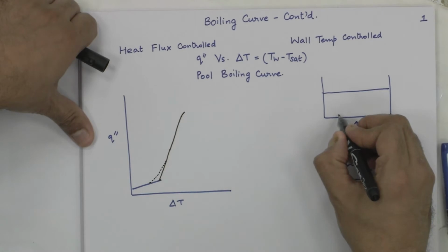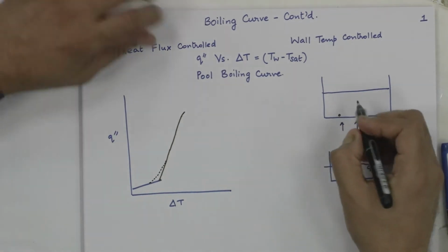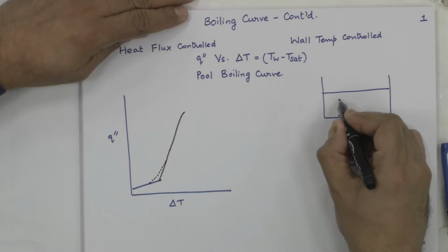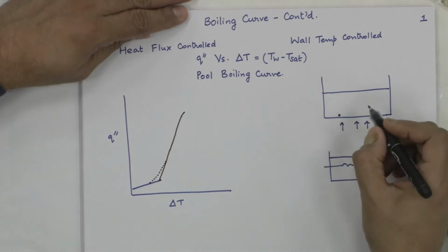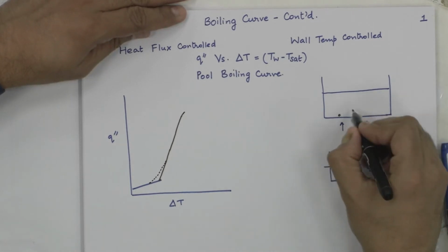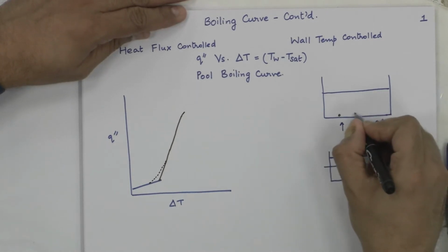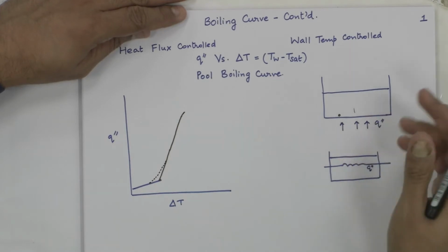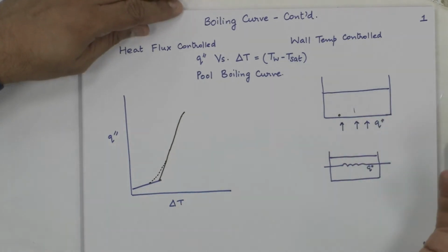where partial nucleate boiling would represent growth of bubbles from the surface, maybe leaving the surface or leaving the surface and collapsing after a certain distance into the pool. When several bubbles are formed at the same time and they migrate to the surface, what you see is typically nice saturated nucleate boiling.